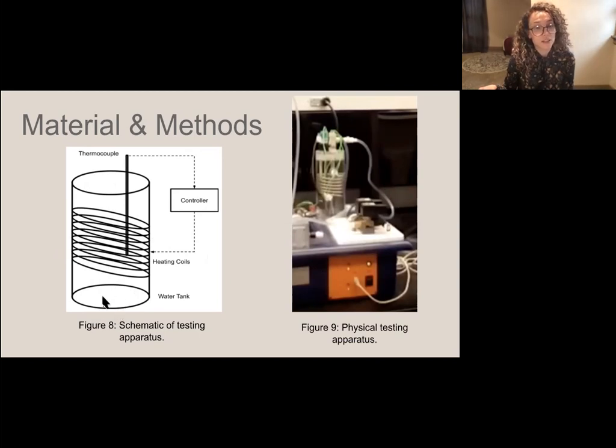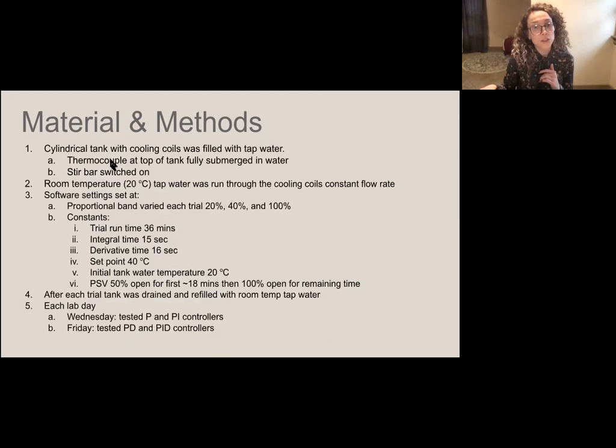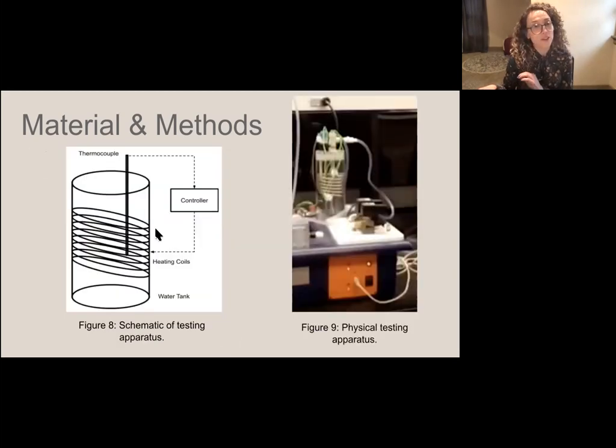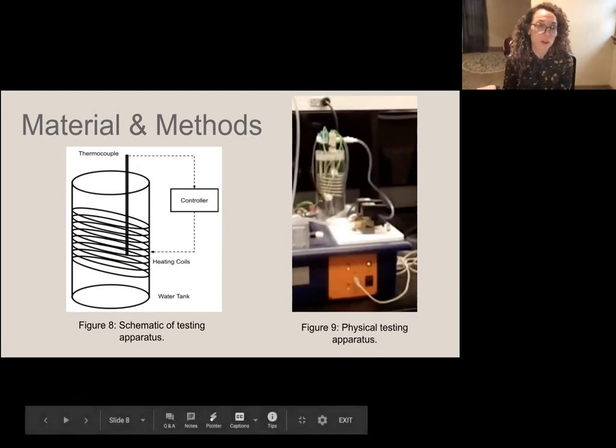The water in here is also being stirred. And there's a thermocouple inserted at the top. That thermocouple is communicating to your software, then to your controller, and then it goes back into the system and tunes it out, helps it go back to the set point.